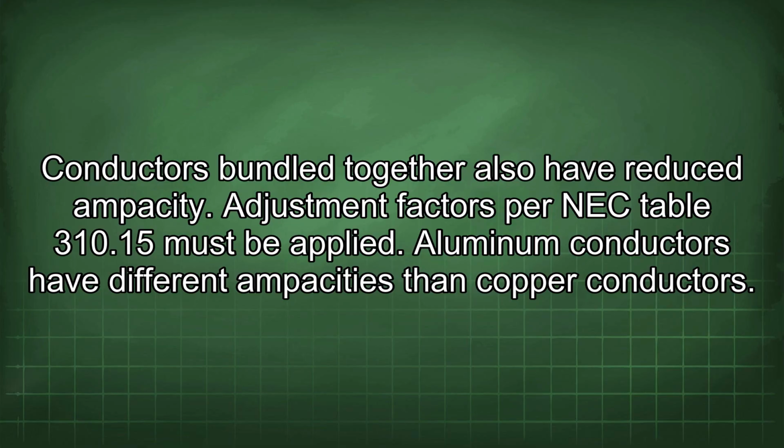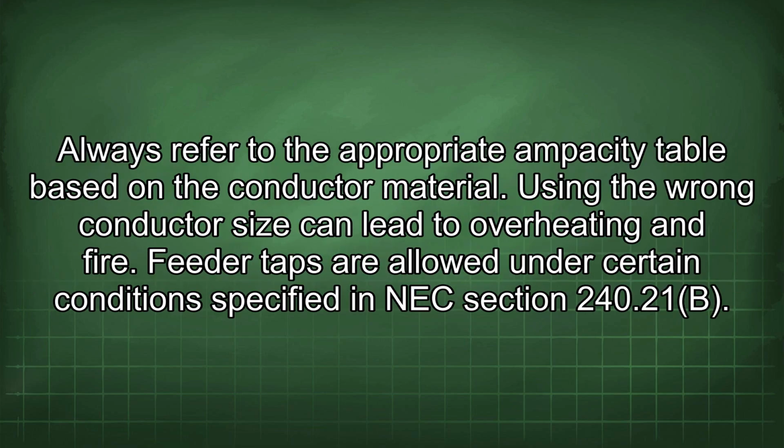Aluminum conductors have different ampacities than copper conductors. Always refer to the appropriate ampacity table based on the conductor material. Using the wrong conductor size can lead to overheating and fire.